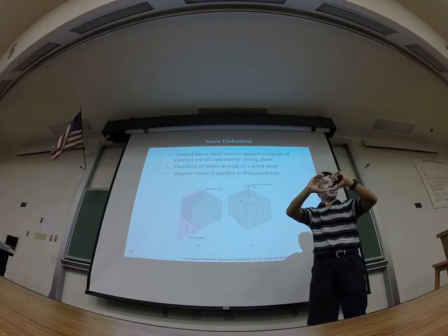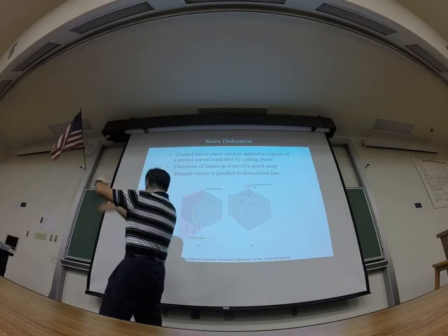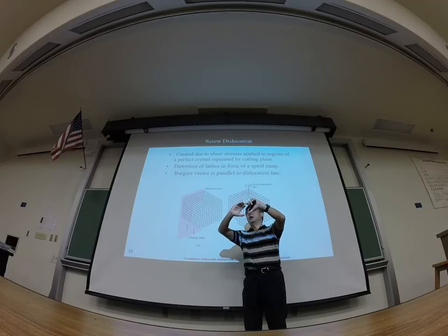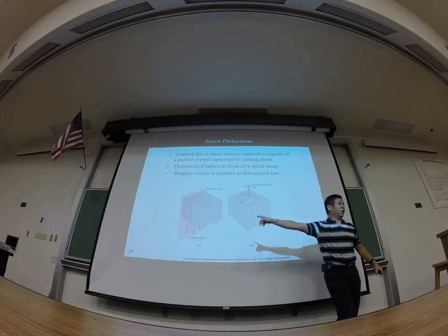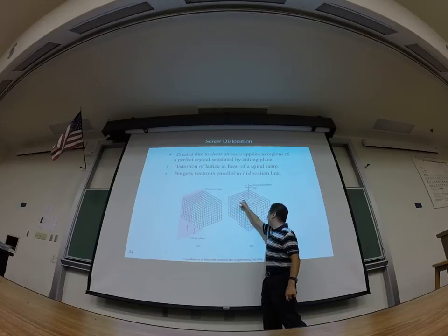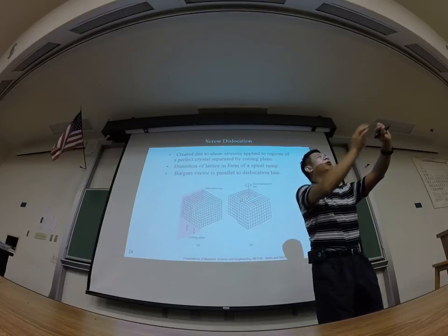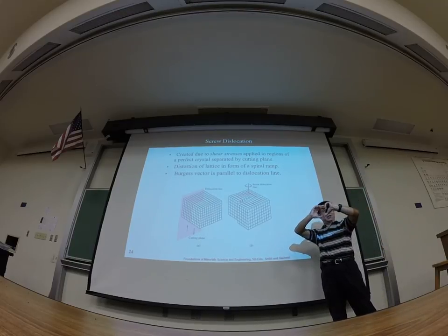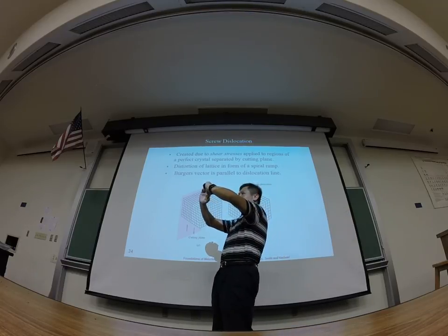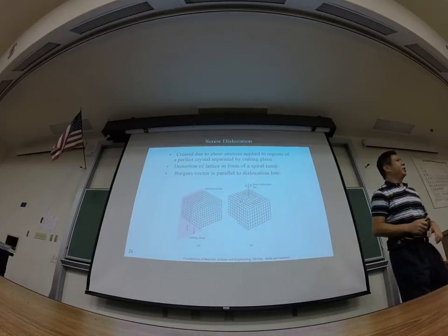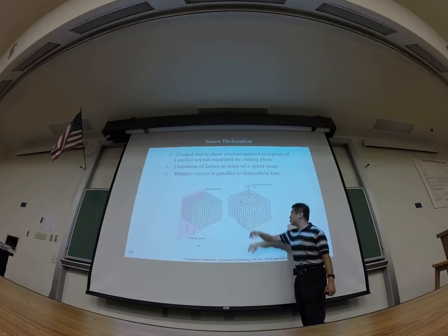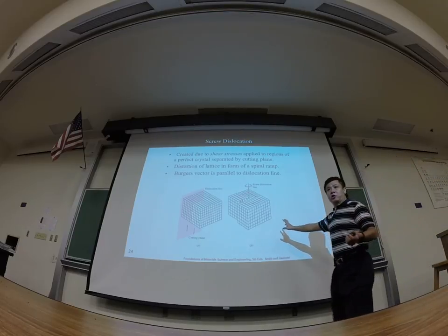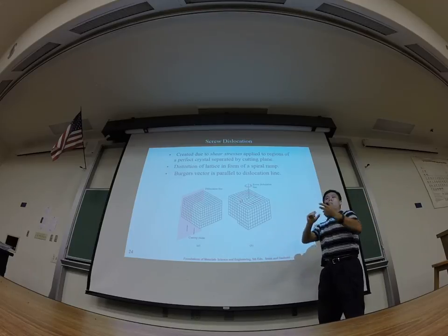there's another way related to the line defect formation. If you have a perfect plane, if you imagine about that one, if there's a surface being inserted into that, and then we twist the crystal, one is up, one is down, you will generate these kinds of defects, right? So indeed, between these two lines, you will see this kind of interfacial area. Those areas will also represent line defects because you will see a dark line under the SEM. That one is because of a shear, right? When you're applying a shear force to the crystal, when they twist it a little bit, we call that screw dislocation. Once again, we can use these Burgers vectors to represent that. This one is parallel to the dislocation line, but that's too much. I just want you to know about that one. So there are two ways for generating line defects. One is twisting. One is more like on the plane.